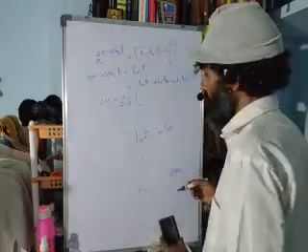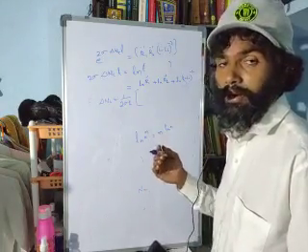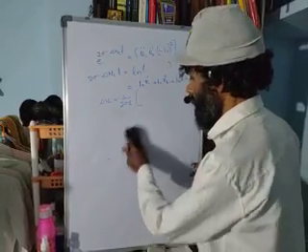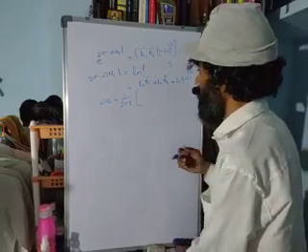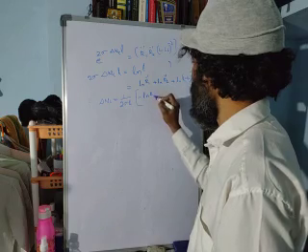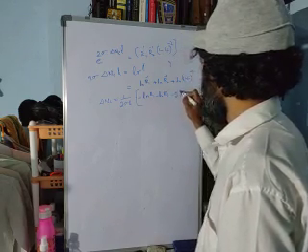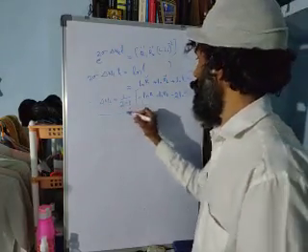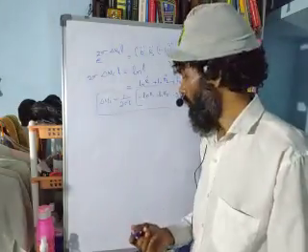Of course, it comes again from the same thing which we used, ln ab is equal to ln a plus ln b. So anyways, because of that property of logarithms, we can write this thing as minus ln r1 minus ln r2 minus 2 times ln 1 minus li. So this is actually the equation which we call the condition for threshold inversion.